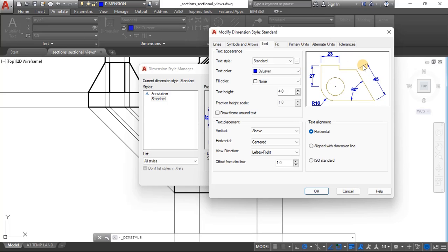No matter how you are dimensioning that part, text is always vertical. So that is the unidirectional system, and the other system is the aligned, where the text is placed above, on top of a dimensioning line. In order to achieve that, make sure you either click this, and then default is that, which is like a mixture of some sort.